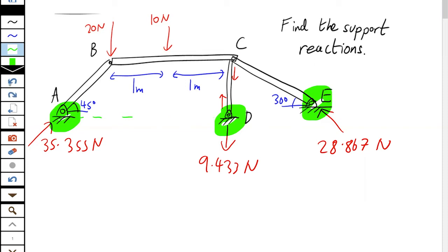If you were able to say that, you'd have a continuous piece of ground there, because you see that ground definitely doesn't line up with E. Maybe they accidentally are at the same height. If you do the math, if you're given distances, it might turn out, but just be careful. If they don't show that they're on the same piece of ground, you just can't assume that. So that's a nice little extra tip there.